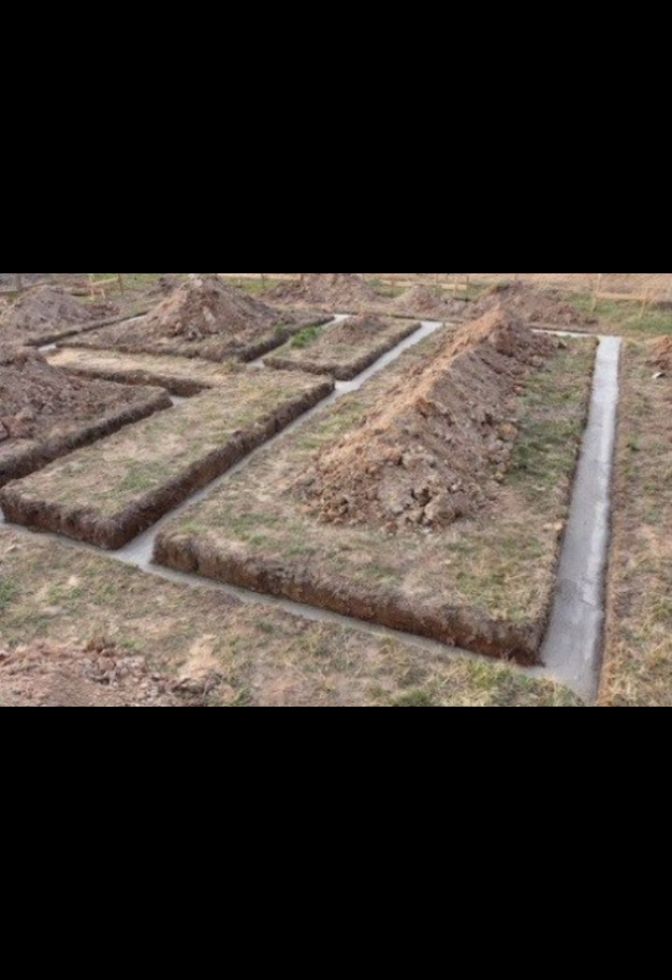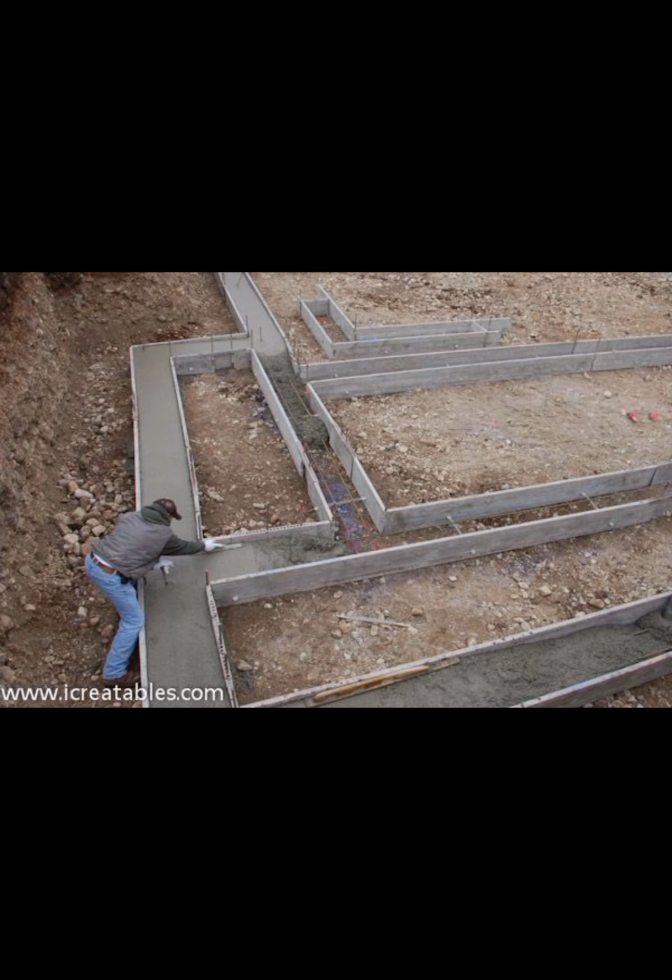First of all, the trenches are dug along the place where you're going to put your blocks. Secondly, concrete of your desired mix ratio is mixed and then poured into these trenches. So you either decide to put reinforcements or not.